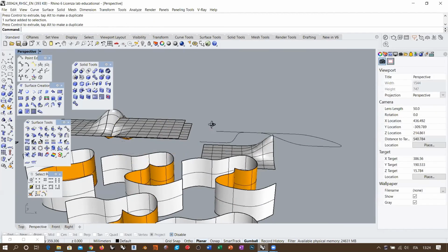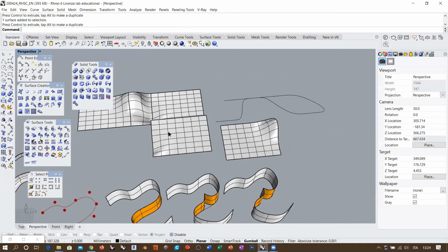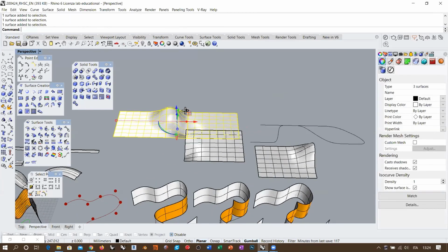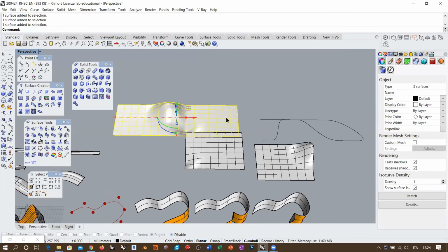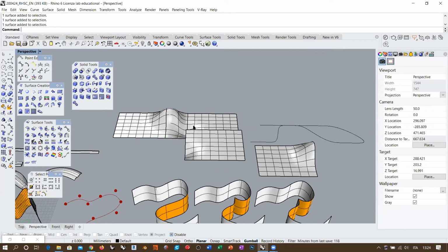Dan, before you finish the explanation, can you repeat quickly the question so we can follow? The question was if it was still possible to merge the surfaces. And merging the surfaces gives us, as a result, one single continuous surface instead of three separate surfaces, or one polysurface. Okay. So the goal is to have one single surface in order to perform easier topological operations.